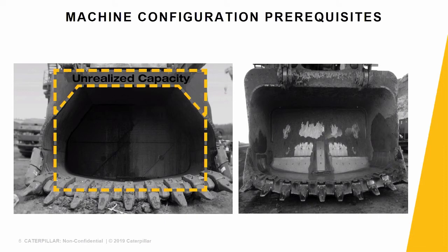It's surprising how many mines we find opportunities from reevaluating how well their shovel, their dipper, bucket, and truck align with the different fragmentation and the range of densities. So they were engineered, but nobody goes back and looks at it. So it's good to do a scale study, verify those densities, reconfigure it, and look into those things.